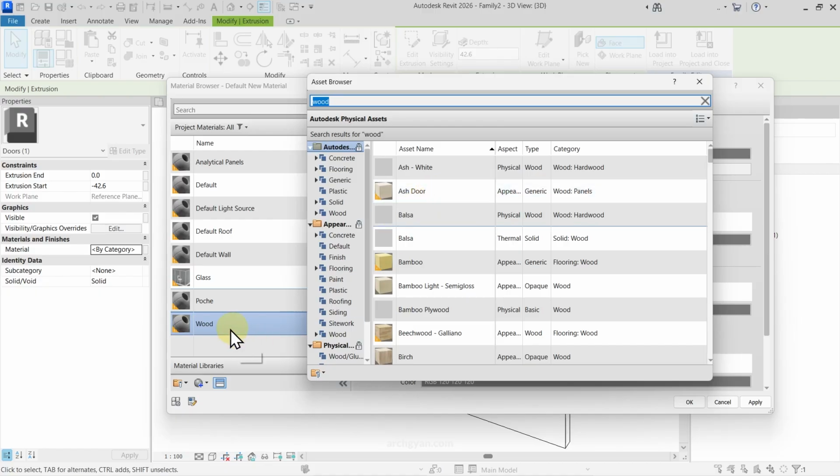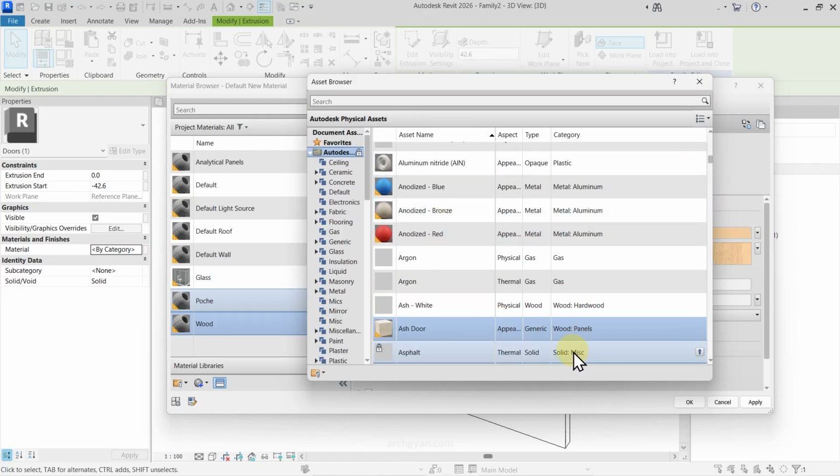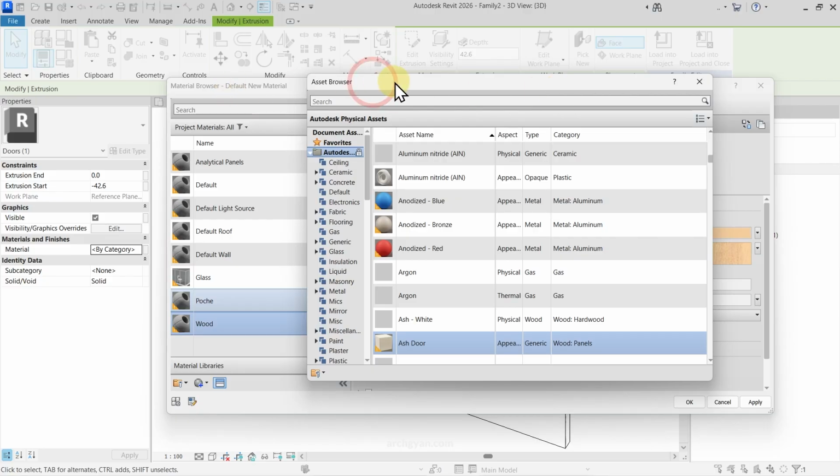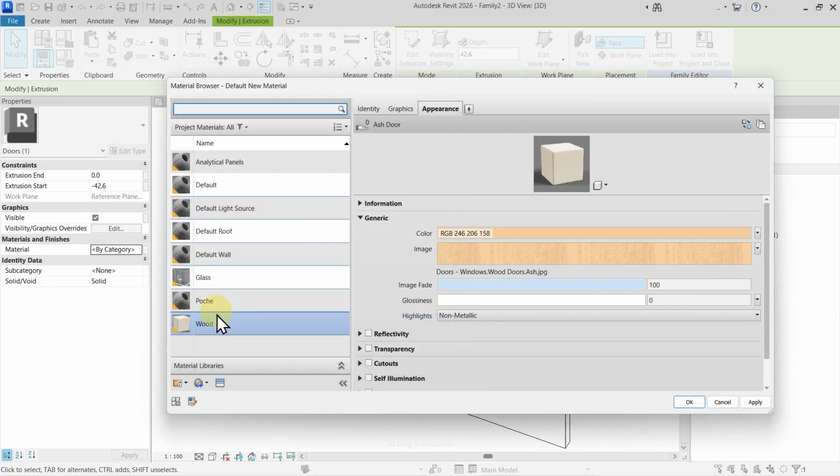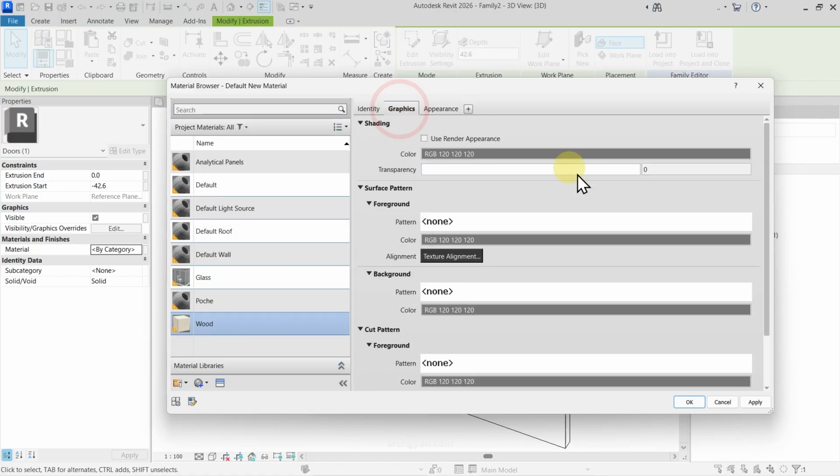If you want to replace the new material with this material, on the right, we have this replace the current asset in the editor. So click on this icon. And then you will notice that it automatically gets replaced here. So the wood material changes with the settings in our asset browser.